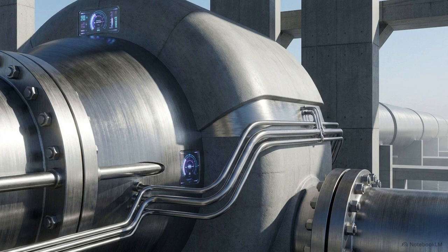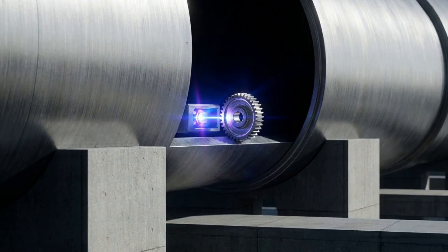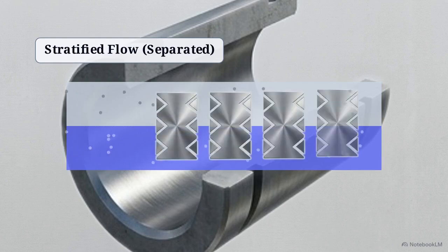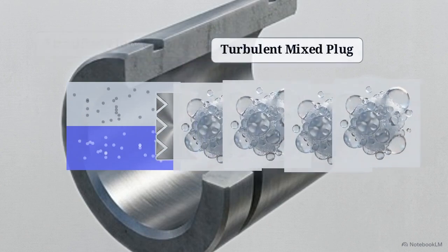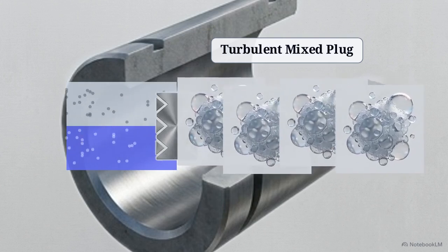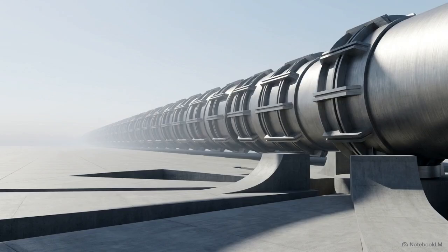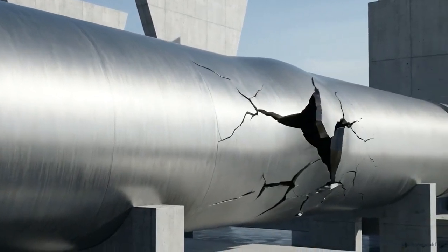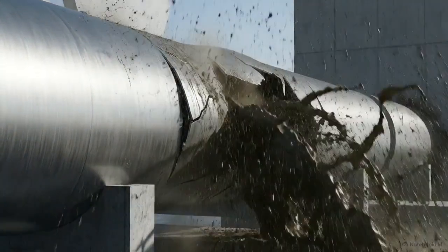The steady-state requirement itself is a mechanical vulnerability. Pushing fluid forward with absolute, unchanging consistency demands extremely precise and often highly expensive continuous flow control pumping hardware. Multi-phase reactions, such as complex gas-liquid mixtures, further complicate the internal design. Running these requires specialized internal baffles and structures just to prevent the phases from separating as they travel. The continuous tubular reactor is a highly precise architectural instrument. Its efficiency drops to zero the moment the physical properties of the fluid deviate from the mathematical boundary conditions.